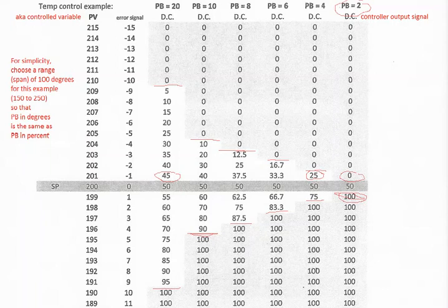That's another basic concept to always have in your head when we get to the chapter on tuning. It's just that simple idea that when you crank up the gain high enough, you will cause oscillation, and you're basically looking at a controller that's doing on-off control.